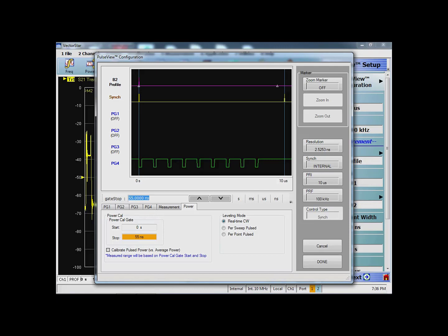Sometimes customers also ask me, can I apply an amplifier in your pulse modulator test set? The answer to that question is yes. As you can see in this image, we have dedicated ports for the high band, which is above 2.4 gigahertz VNA, and for the lower band we also have an LB amplifier port 1. So the customer can do an amplifier insertion at those places.